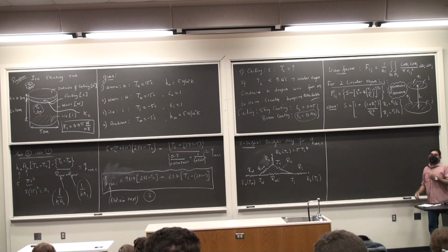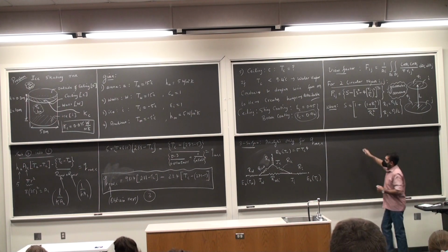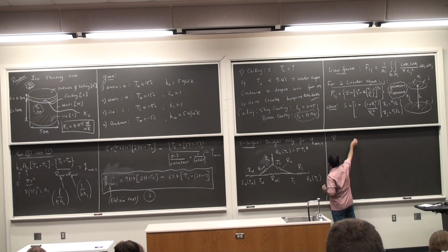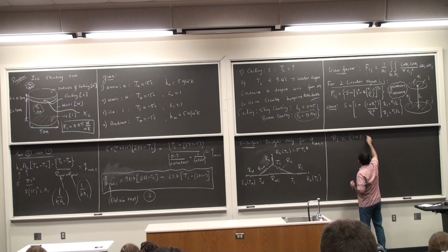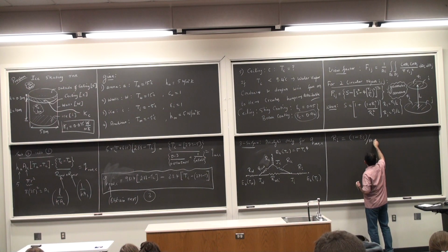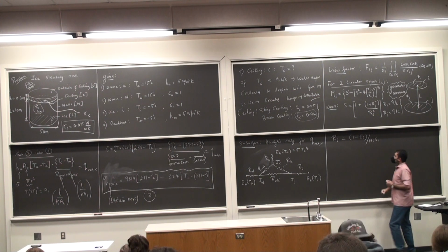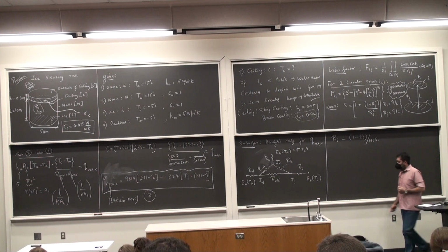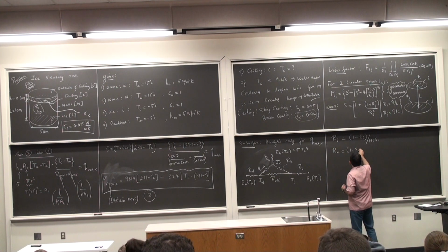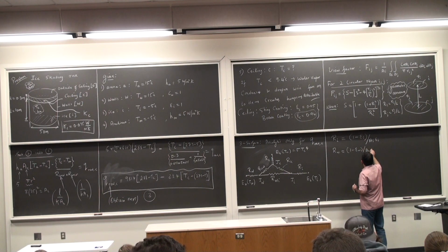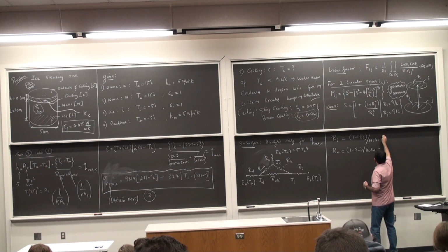And I'm going to list each of them. So I have Ri is 1 minus epsilon ice by Ai epsilon i. Then R wall and Rc likewise. 1 minus epsilon wall by A wall epsilon wall.